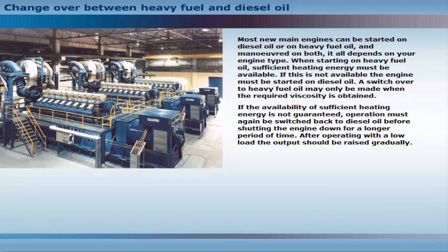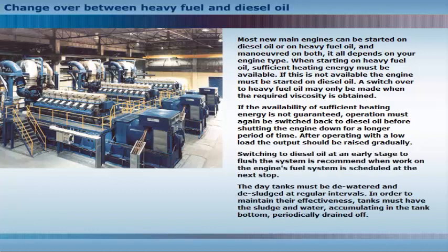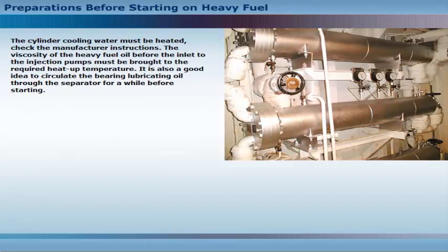After operating with a low load, the output should be raised gradually. Switching to diesel oil at an early stage to flush the system is recommended when work on the engine's fuel system is scheduled at the next stop. The day tanks must be dewatered and desludged at regular intervals. In order to maintain their effectiveness, tanks must have the sludge and water accumulating in the tank bottom periodically drained off. The cylinder cooling water must be heated.